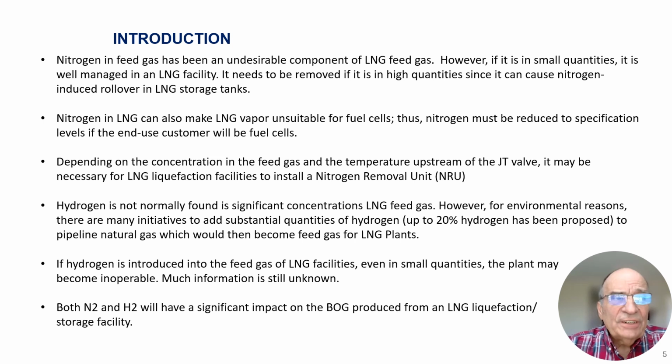Unfortunately, hydrogen and nitrogen sound so similar that I may have to designate it as nitrogen with an N or hydrogen with an H during this presentation. Small quantities of nitrogen are usually found in natural gas, and they are undesirable when they go into a liquefier because they decrease the efficiency of the liquefier and they end up increasing the nitrogen content significantly in the BOG, that is the boil-off gas.